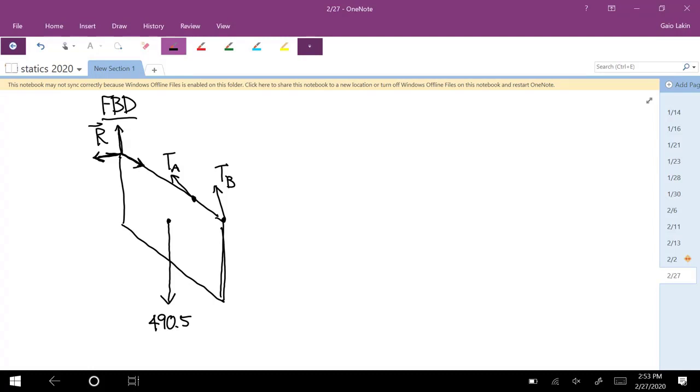5 in this case. And so this is something that's going to be pretty common in 3 dimensions that we really never see in 2-dimensional stuff. And that is that sometimes, pretty often, not all of the 6 equations are going to be useful. What we're most likely going to see is that one of our 6 equations, when you write it out, just ends up being 0 equals 0. And so we're going to have actually only 5 useful equations to solve for 5 variables. Okay.